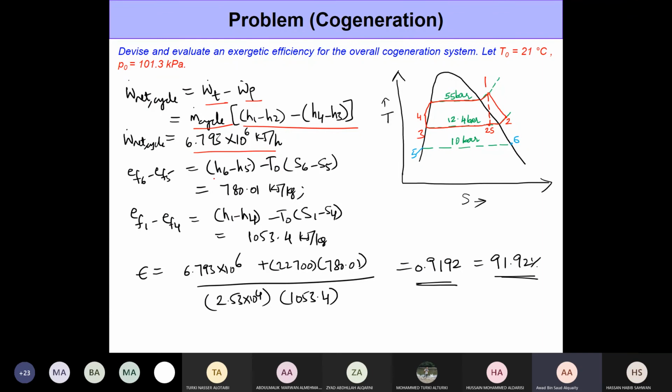Okay. Now, the other thing that we need is the change in exergies. The change in exergies are also easy to determine once you have the enthalpies and the entropies. All right, and we picked up these entropies directly from the table. So we have the enthalpies and entropies for all the four states, just a matter of plugging in the numbers in this formula, and you get the exergy changes for both the process stream here and for the working fluid here. Okay, so once you plug in the numbers, you got to be careful to make use of the correct mass flow rates. This is the mass flow rate of the process stream. This is the mass flow rate of the working fluid.